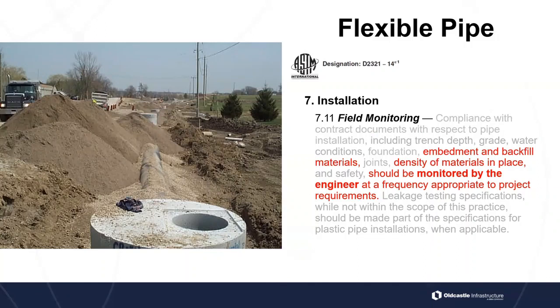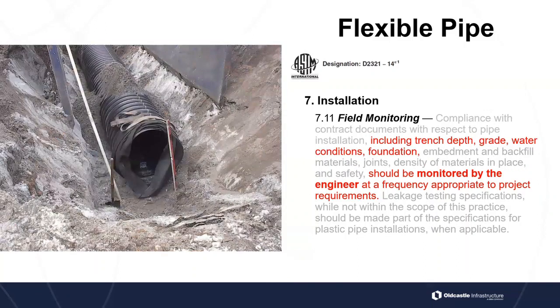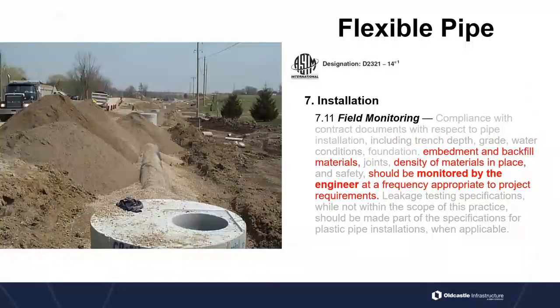You've got a lot of material being pushed on the side there, that flexible pipe, as that material is dumped there and it moves, is it going to lift that pipe up? Is it going to shift it? Is it going to move it? These are all things that we need to look at when we deal with embedment, backfill materials, the foundation, making sure that it's correct, right? As we look at that trench materials in the foundation there.